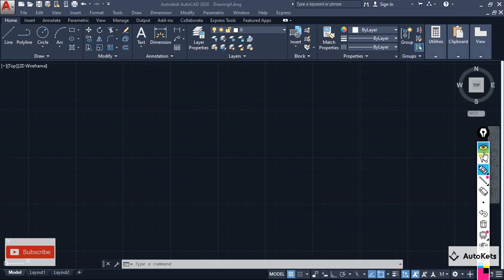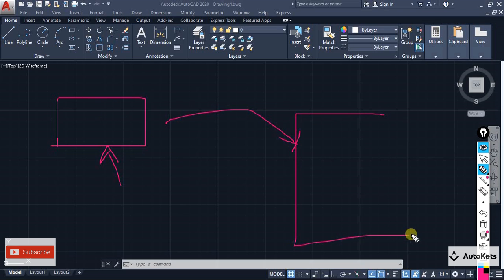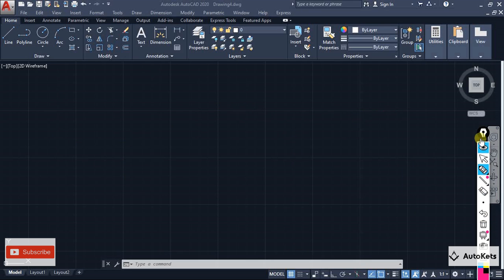Similarly, in AutoCAD also, you can embed a file. Let's say you have created a video and you want to embed it into AutoCAD. That also you can do. Here you can't play this directly. It is going to generate a link. You have to click on that link and the video will open. It's not that the video is playing in AutoCAD. And then we can even embed any Word file or any other software files. So let's see how to do that.